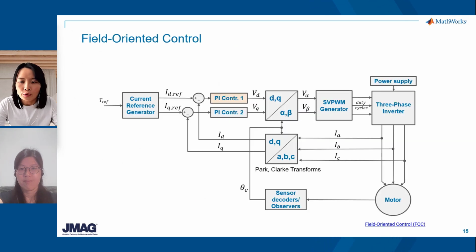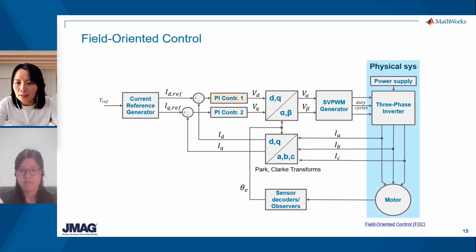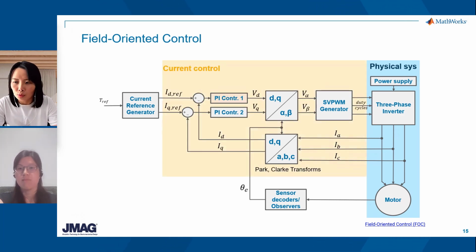Thank you, Yoko. So the next step is how do we implement FOC torque control with a high-fidelity motor model? Here is the field orientation control architecture. On the right-hand side, we have our physical system of a three-phase inverter to drive the motor. And here we have the PMSM high-fidelity motor model, already modeled in the Simscape Electrical block. Our goal here is to use FOC to control the torque.